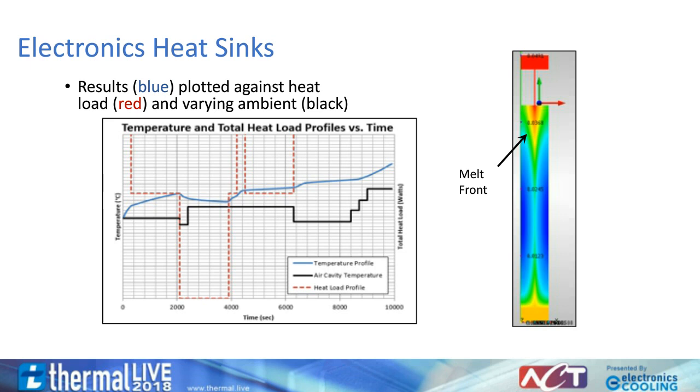One can see through the varying heat loads of the dotted red lines, the blue PCM remains relatively constant and at a slightly higher temperature than ambient. The relative rapid rise of the blue PCM at the end of the graph is an indication that all of the PCM has melted and could be in a runaway condition. Fortunately, in this case, the on-cycle has ended and the PCM will begin dissipating heat.